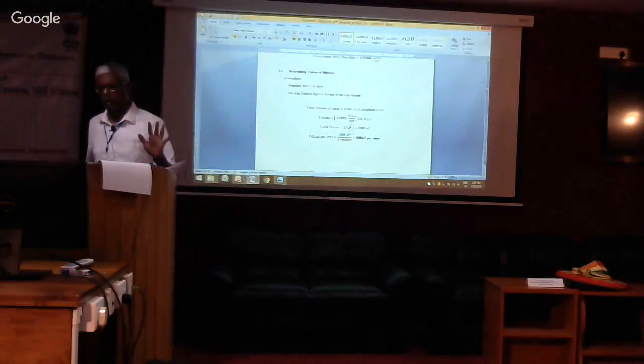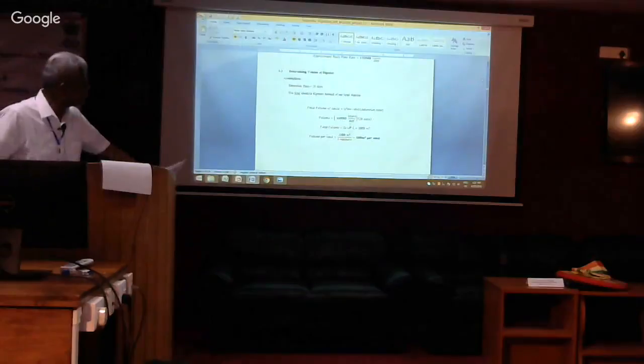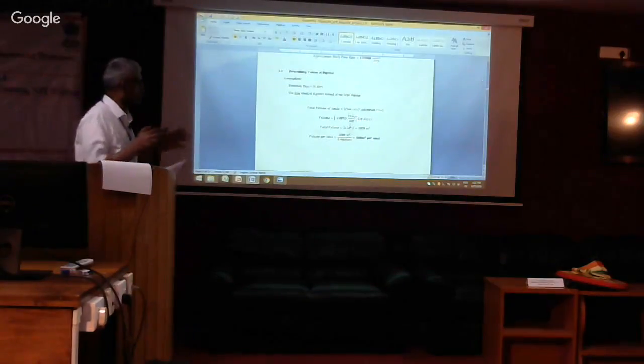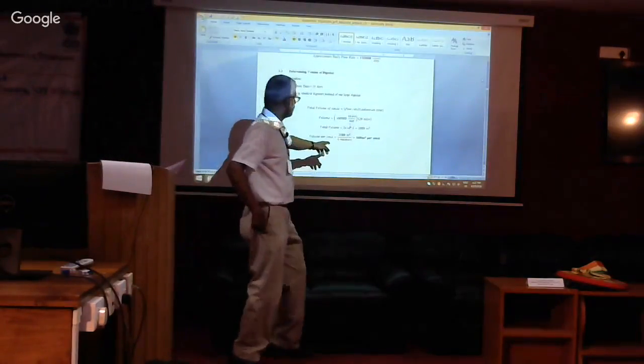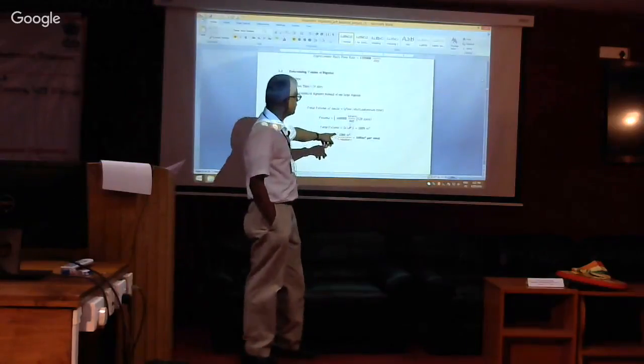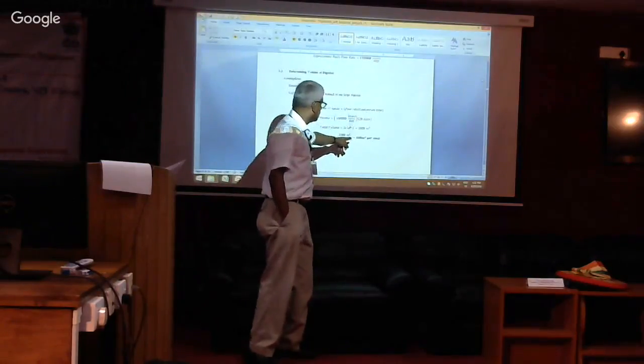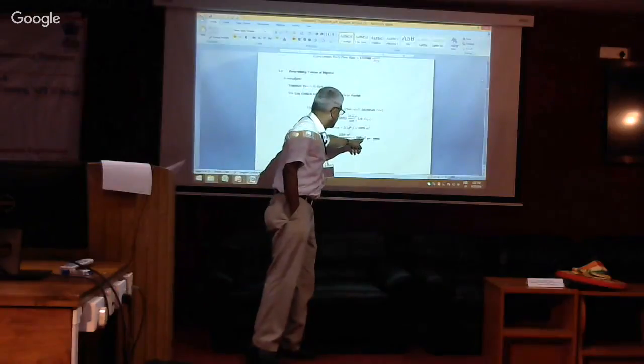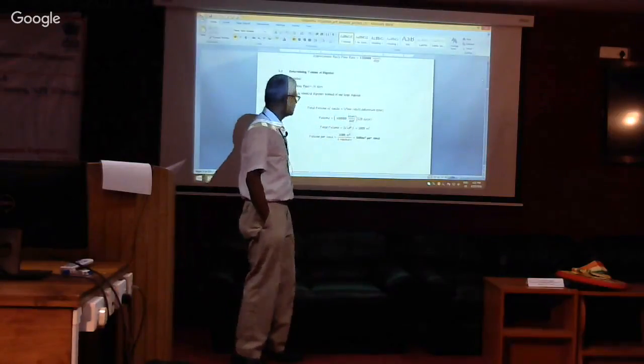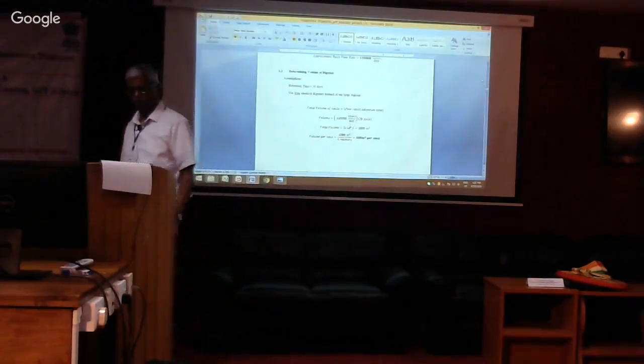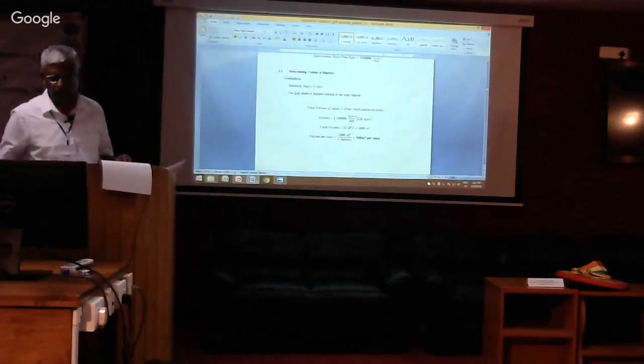And of course, when you say we will use 4, you have to provide for a realistic purpose at least 5 reactors, 1 being standby. So our calculations would be on the basis of 4. So 4 reactors which run in parallel, and each digester will have a volume of at least 500 meter cube. Okay.